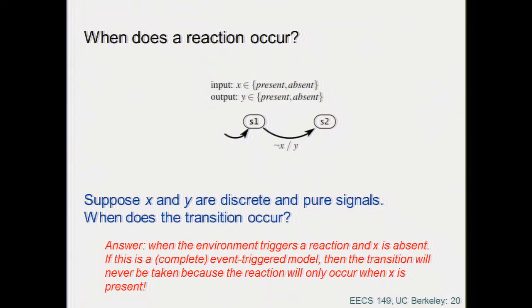So when you have a time trigger protocol, for example for wireless communication, TDMA, time division multiplexing, you have tricks of all kinds, in such a way that not your entire node wakes up when the clock comes in, but only a small tiny piece of the circuitry. Now, if that circuitry detects something, then it wakes up everybody, right? But if nothing happens, it's only that small piece that goes up and down, so power is optimized, okay?